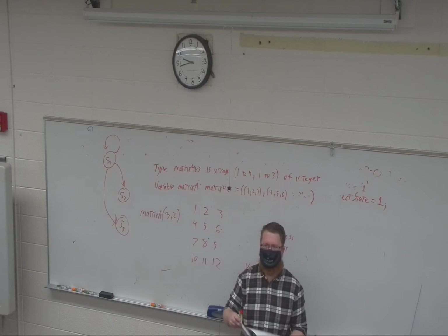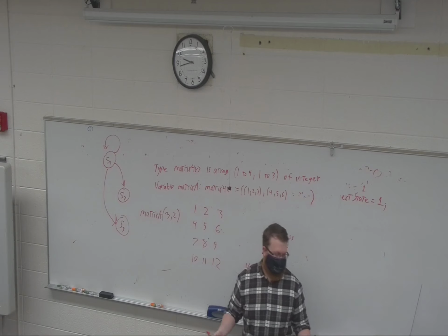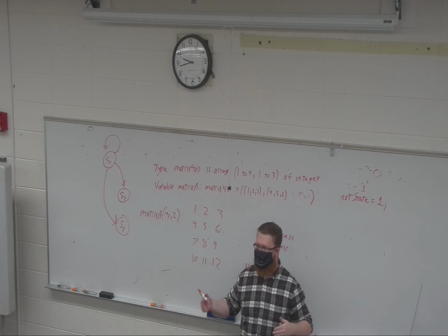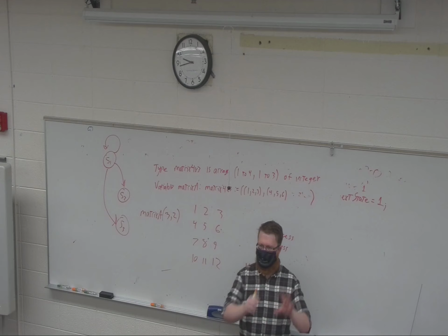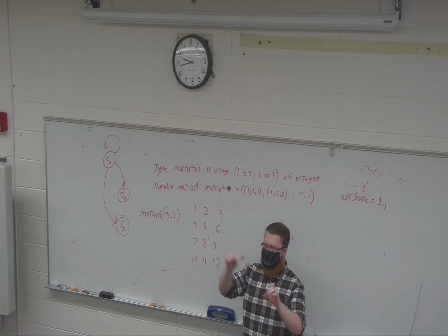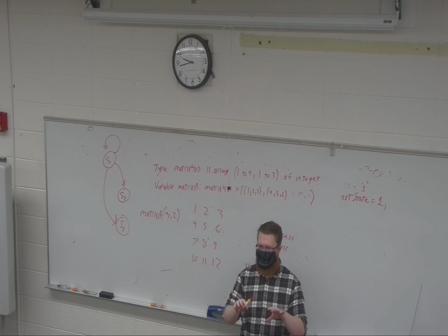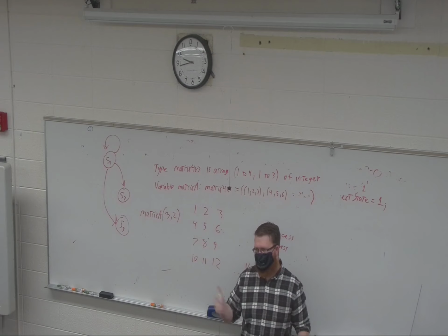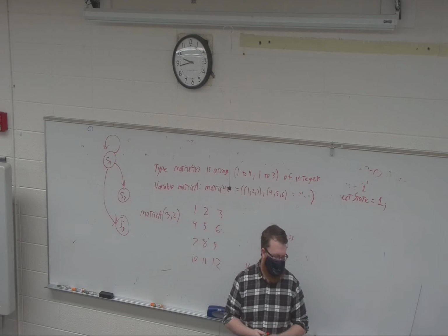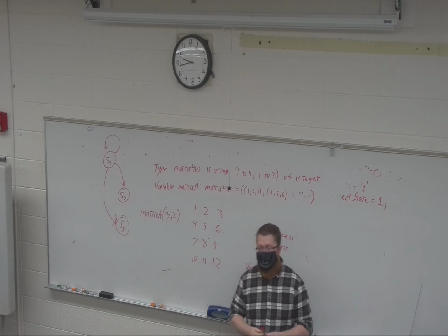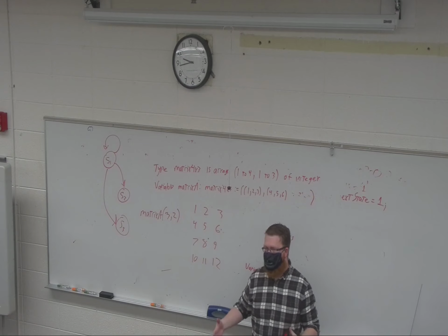If not, it's in the book where you can declare constants. So you could define a constant, say delay. You're going to say, I'm working with a lot of flip-flops, and I'm going to guess I'll have the same delay. So I'm going to create a constant delay, and then every time, instead of having to write what the delay is, just write delay. And it carries through. But what we're going to do now is move on to the description of the lab, because I really want to get this started.